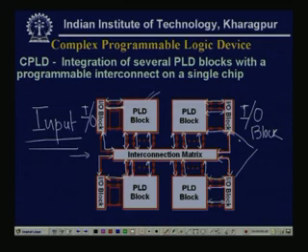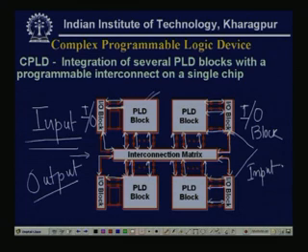Another thing is that, these IO blocks, not only as an example I have told that this can be input. Say from this PLD block some of the things can be the output. Some outputs can be taken from this side, or here also some inputs can be applied from this side. So, it is totally programmable and totally flexible, only this is a compact architecture, with some PLD blocks, some IO blocks and interconnection matrix.